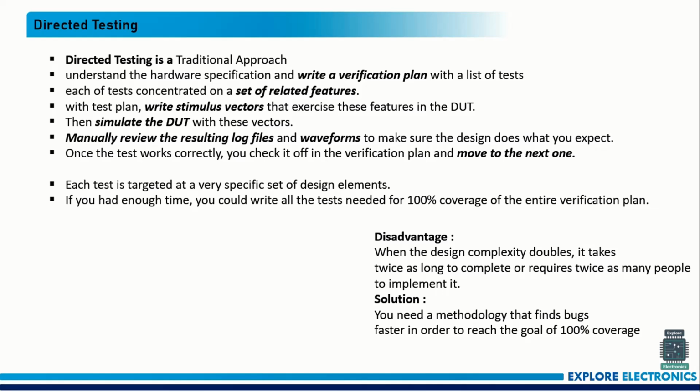What happens in the Verilog test bench is that we directly instantiate our DUT and then start giving values by manually writing them, right? That is the directed testing approach. Here, understand the hardware specification and write a verification plan first. Here also the same steps apply, and each and every test is concentrated on a set of related features.